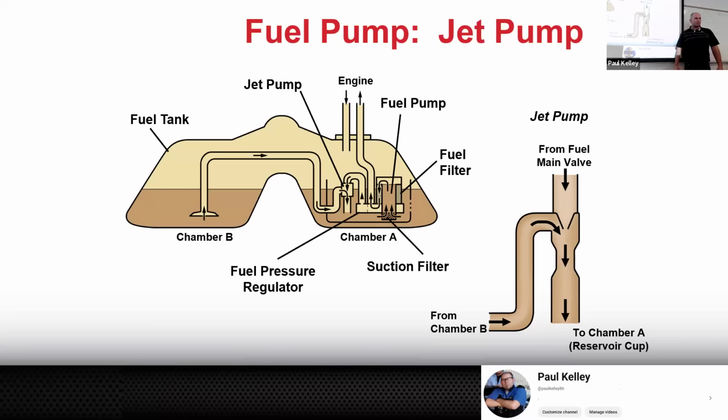You can test that by like turning the key on and off a few times, right? The way that I would test it is I would put a fuel gauge on it. I would turn the key on. Let's say it pumps the fuel gauge up to 50 PSI because that's where the regulator is. Then I would turn it off. I would walk away. I'd go do my work and I'd come back in 5, 10, 30 minutes and I'd see, is it still pretty close to 50? If it's down to 9 PSI, I'd be like, oh, that's draining back. It's an anti-drain back valve. It's a one-way check valve. It should allow fuel out, but it shouldn't allow fuel back in. Yeah, so it's a pretty easy test.